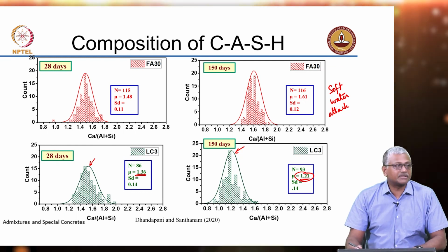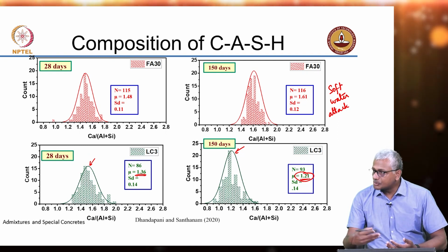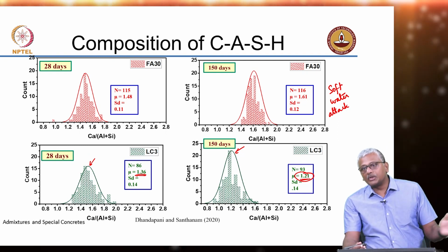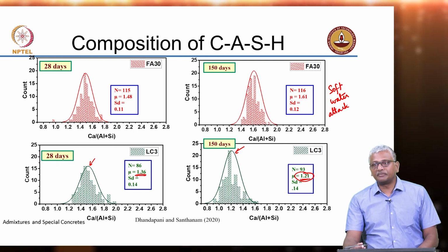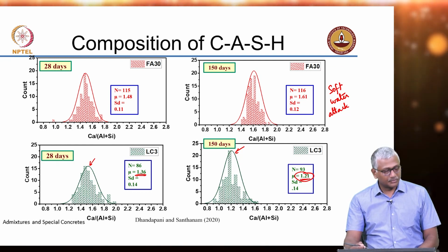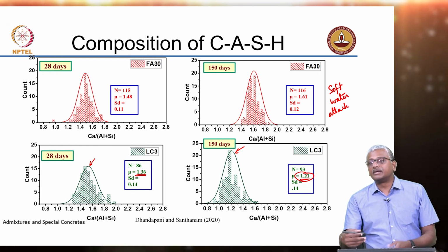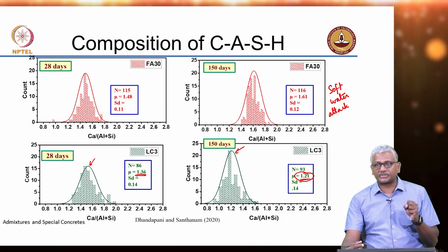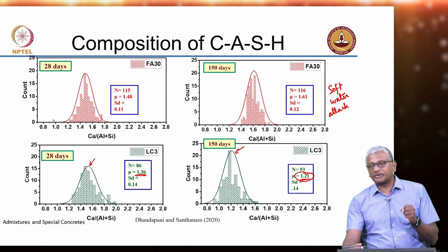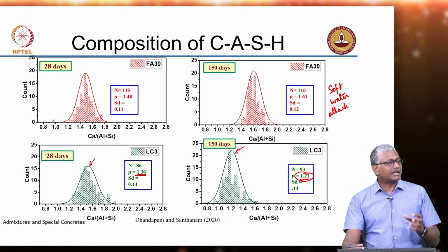But this is not something that produces dramatic effects in a short period of time. This is something that happens over a longer period, where you are slowly leaching out the soluble species from the concrete. So, generally in such situations, the use of blended cements will be beneficial, because it will tie up your structure in a silica and alumina rich product, which will be less soluble as compared to your calcium rich products.